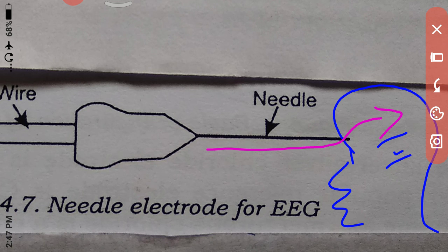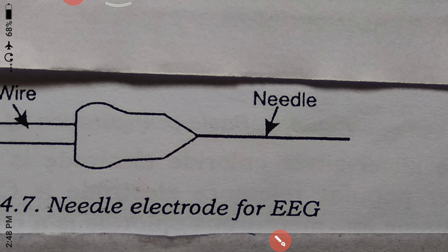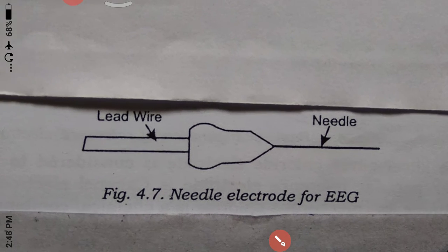For electromyogram applications also, these needle electrodes are basically a fine insulated wire placed at their tips in contact with the nerve, muscle or tissue whose measurement is to be made. This needle electrode can be inserted to measure human muscle potential also.